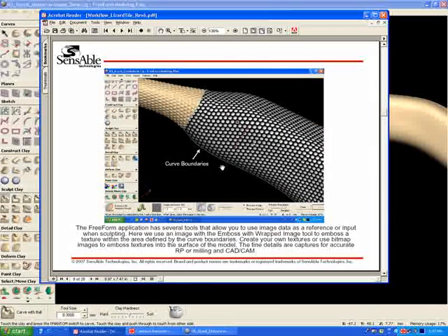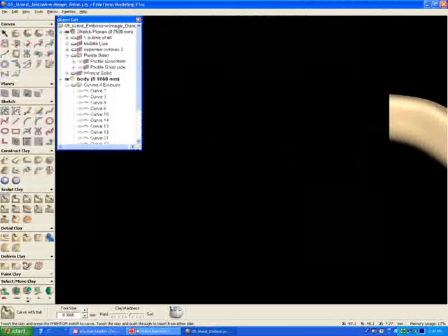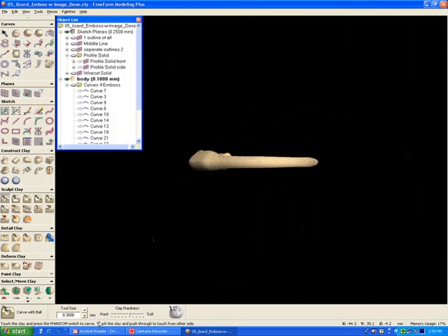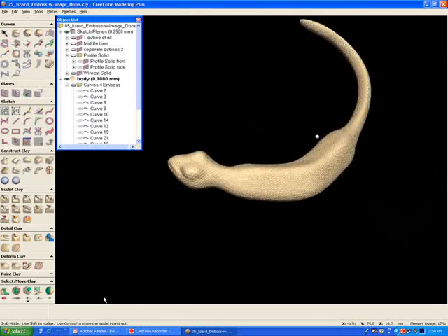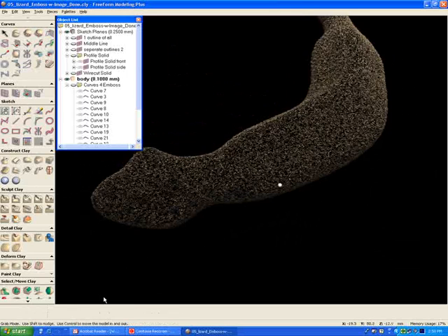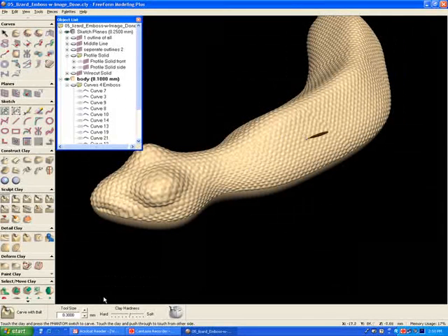So what I've done, I used emboss with wrapped image. That means embossing within a boundary in several parts, and I've also rotated the back part to fit into here. This then results into a 3D model that has structure like that all over the surface. When I now move over the surface using the stylus on the Phantom, I can now feel that there are ridges on that one, while the lower side is absolutely flat and clean.